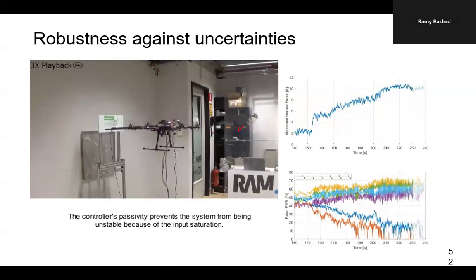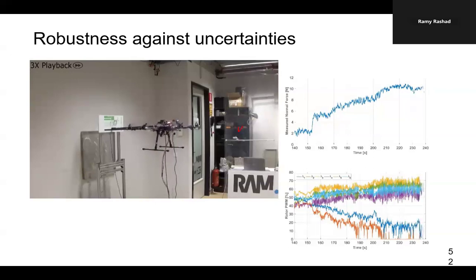It's stopping. Why is that? Because I wanted to push further, okay? And this means that the control allocation part is asking this motor to produce negative thrust. The propeller itself cannot produce negative thrust, so we just say, okay, negative thrust is 0. We just make it into 0.